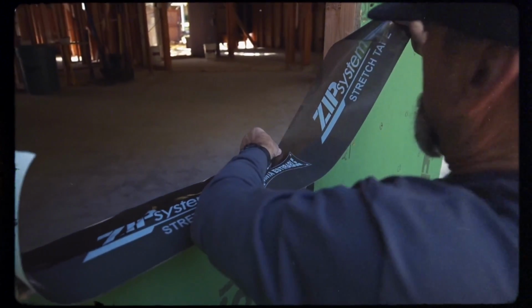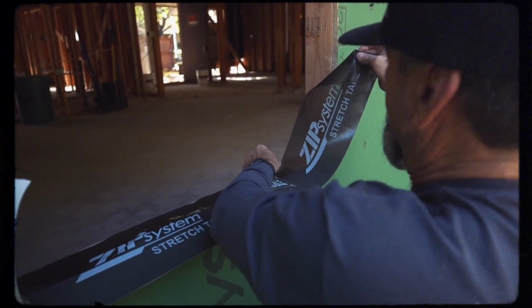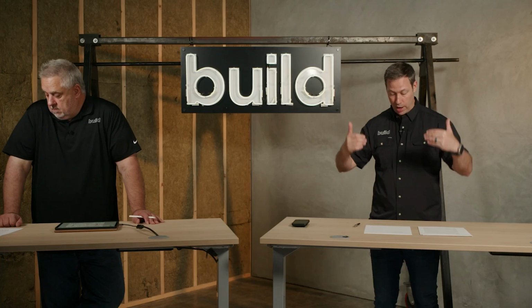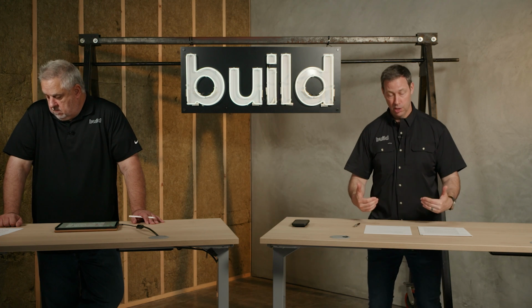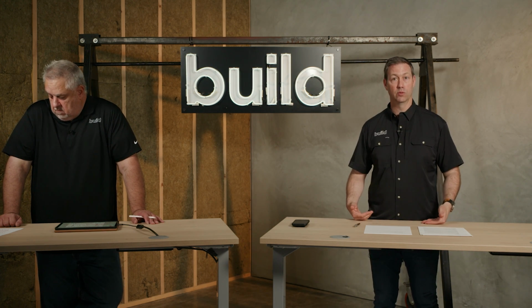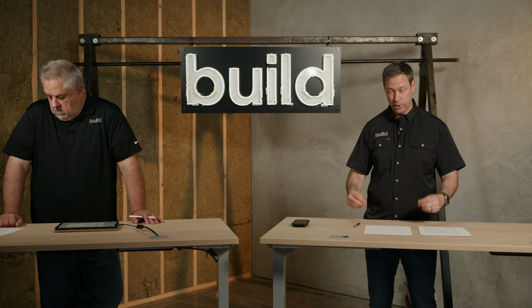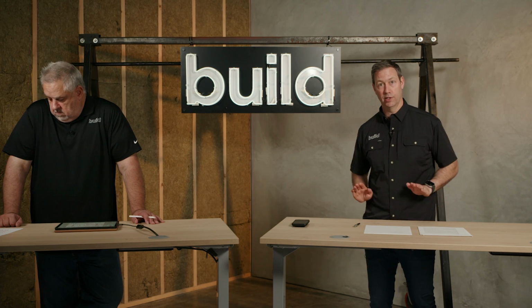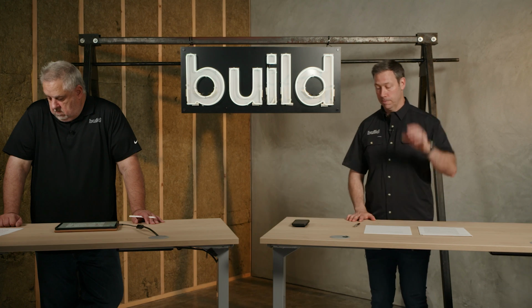Often it's from the same manufacturer. Maybe in an older house it's a metal sill pan, or some of the houses I do will create a metal sill pan, but in a way that if water were to get past that window and leak into that rough opening, gravity is going to bring it down to the sill. So we want that sill to be waterproof. And we also like that sill to have some slope to it, so that if water does hit it, it's going to be sloped towards the outside rather than running to the inside.